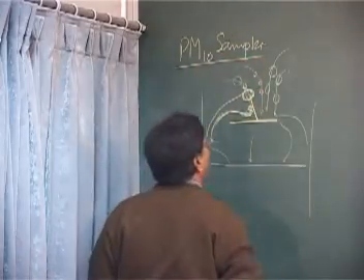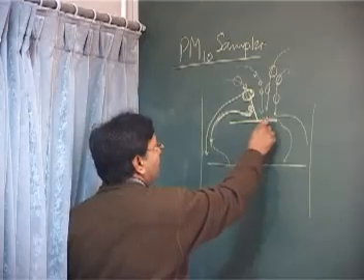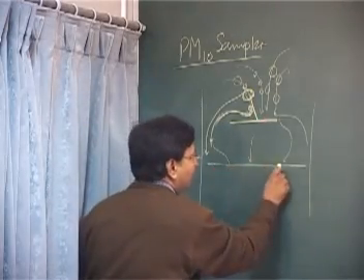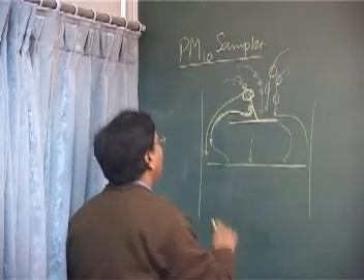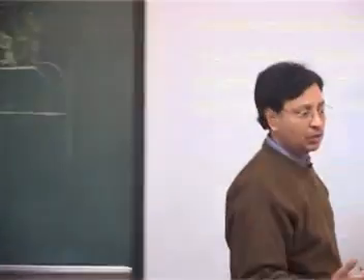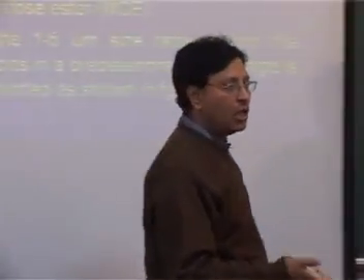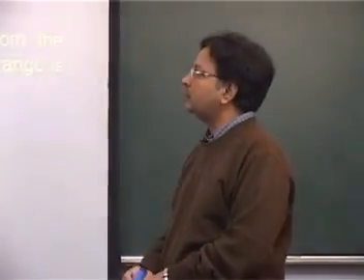Time permitting, I might show you that picture also. So in PM10, all the larger particles will stop and only PM10 particles will be retained here, the particle size less than 10 aerodynamic diameter. You can do the calculation, you can design the things because you know the inertia, you know the general structure of your particles in the atmosphere.